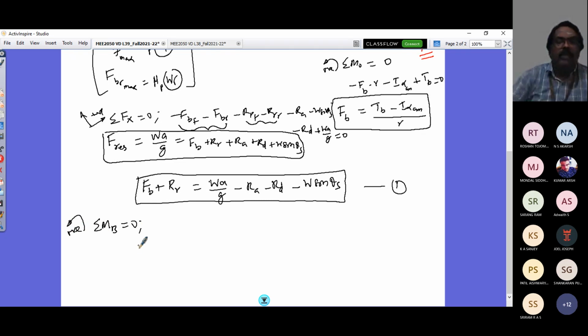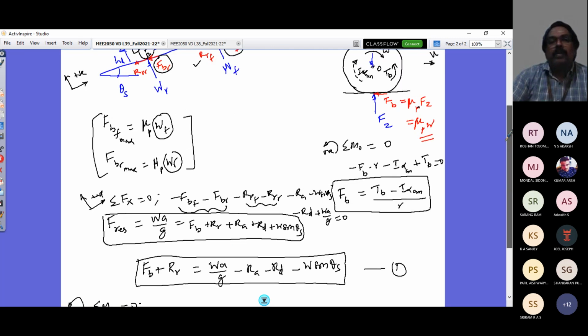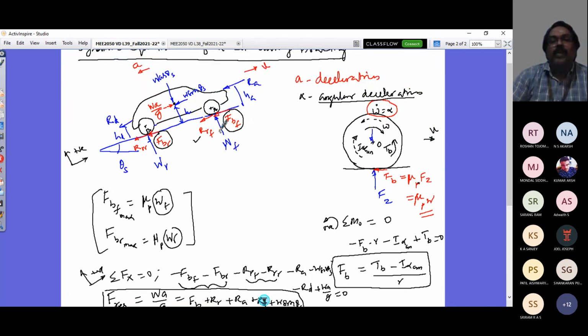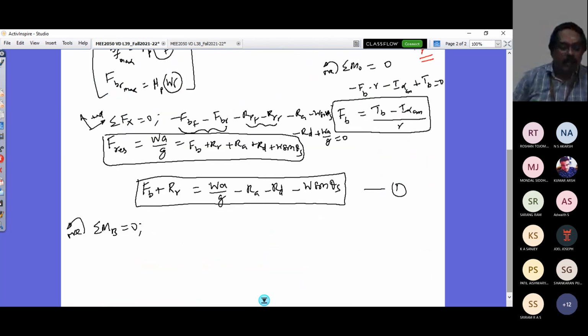So first let's start with WF into L, and one by one let us account for the forces. You can also cross check parallelly. WF into L, where L is the wheelbase, is the moment which I am interested in. So this is a counterclockwise moment.